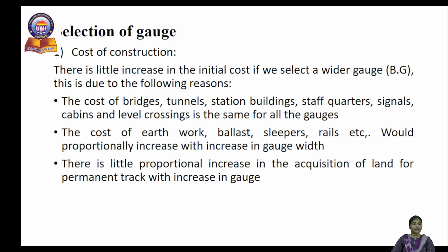So how to select a gauge? Based on what factors do you need to select the gauge? The first point is cost of construction. The cost of construction increases as the gauge width increases. There is a little increase in the initial cost when we select a broad gauge.